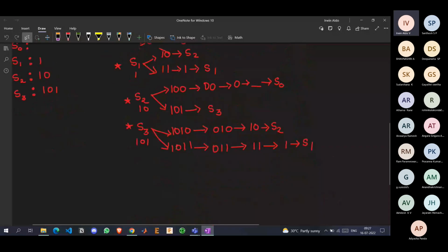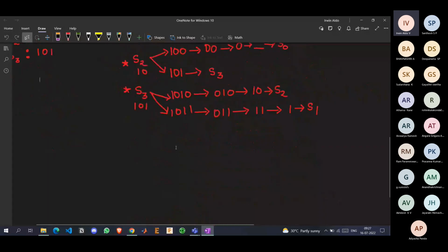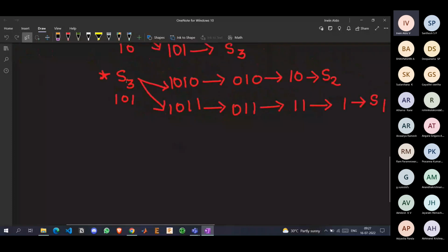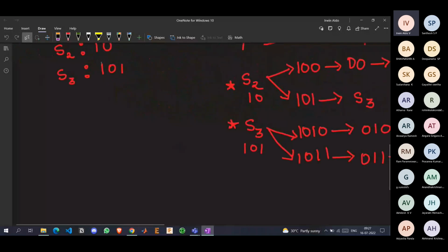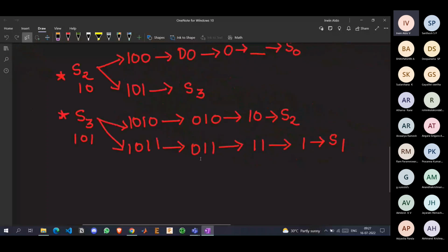Now we will discuss the last and final state. Our sequential circuit should detect continuously. It's not like once I detect, I will turn off. Like every digital or sequential circuit we are going to make, it will work as long as we provide the clock input. So we will start with S3. S3 already has a value of 1 0 1, right? It's our final state. After going to the final state, there are again two paths, 0 or 1.